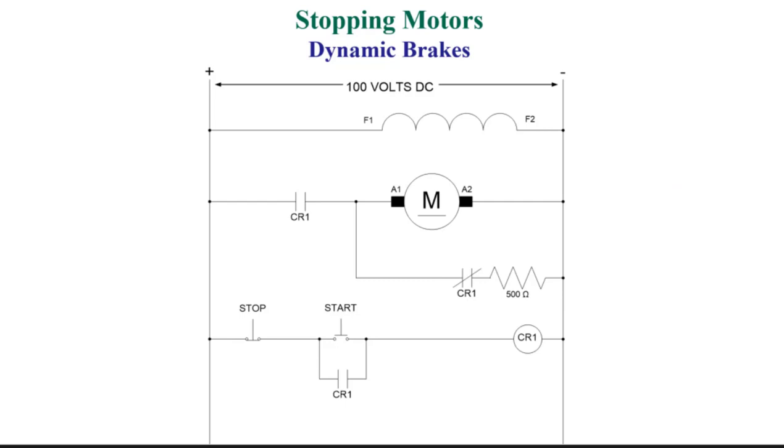In the case of a generator, as you recall, I've got my field poles, just as I do in a motor, that sit around the outside edges of the motor case. And inside I have my windings on the armature. And I'm going to turn those windings with a prime mover, causing those windings to cut the lines of flux that are being created by the field poles. And in doing that, I'm going to induce a voltage into those windings. Okay, so that's how we generate.